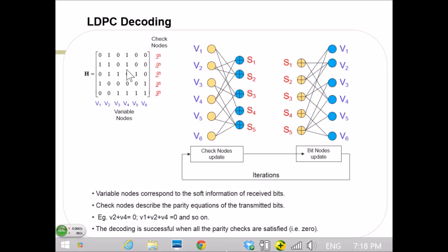You send 1 bit, and there is no code rate because you haven't specified the parity and the data. Actually, it's a 1 by 6. Where's the data? Where's the parity? If I encode that, how do I encode it? No, it's a 1 by 6. So you have 6 bits you're transmitting, and then 5 parity bits. So for every 1 bit, you're adding 5 parity bits.